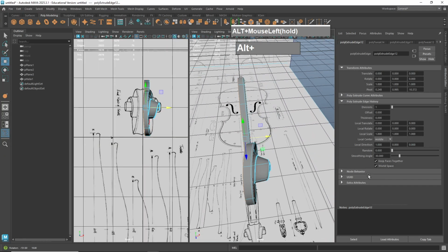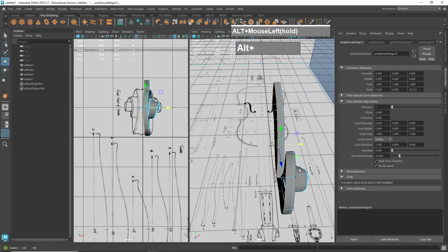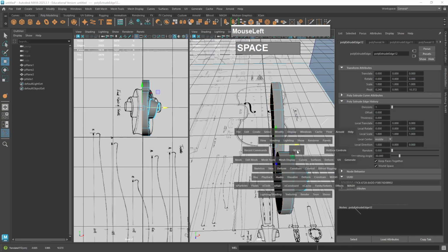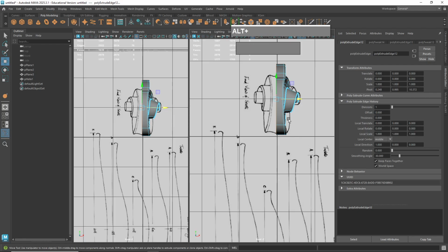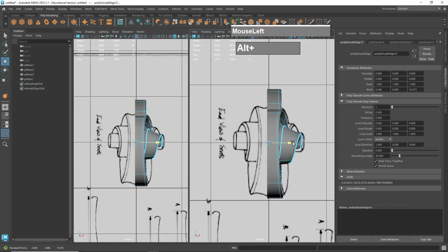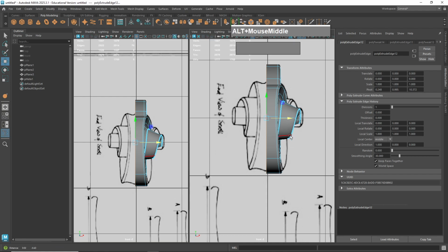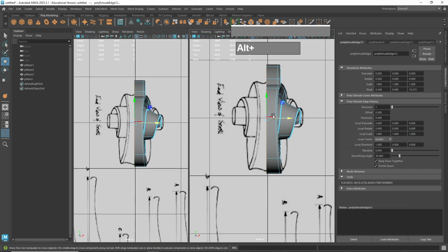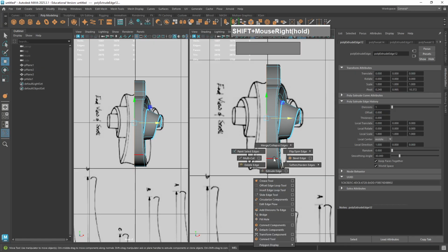Okay. Then while the entire edge is still selected, we can use scale and force all of them to line up together in a straight line. So use the scale to flatten it. Then we can put this in the center. Alright, so now you can see we created the scroll, and also if you need to add this depression here, we can add another continuous edge loop around here to push it in. Which is what I'm going to do right now.